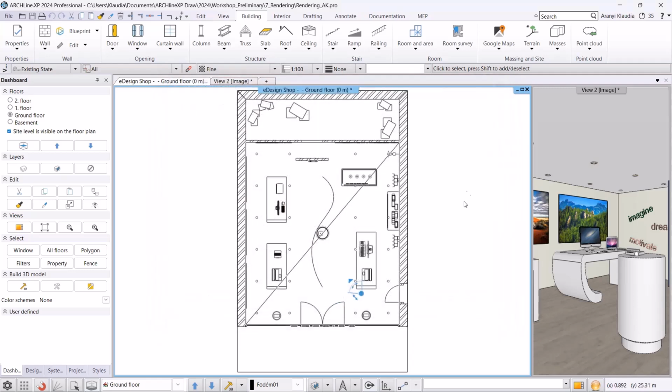The other two factors that affect rendering time are the complexity of materials and lights, as well as rendering settings. When it comes to rendering settings, it is important to consider the resolution and the chosen rendering preset. Now let's see how we can save rendering time. In a project with multiple rooms, it is advisable to disable the layers of those rooms that will not be visible in the render. Within a single room, it is recommended to use 3 layer groups and divide the rendering process into different phases. This way, the rendering time will be much faster compared to test renders.